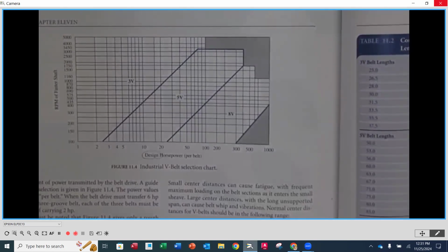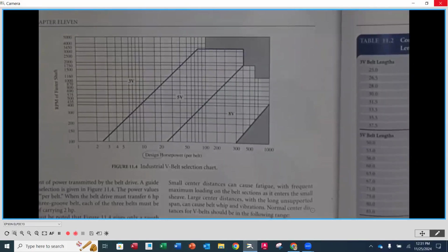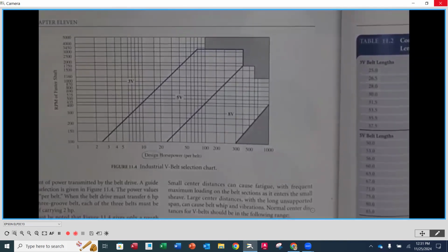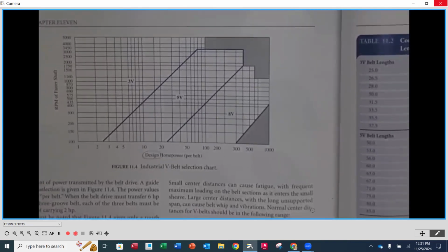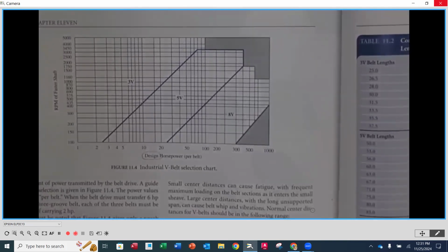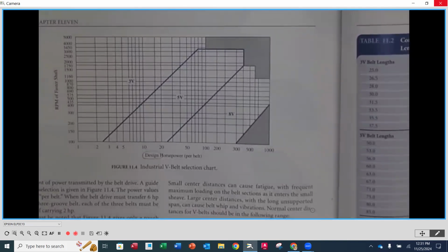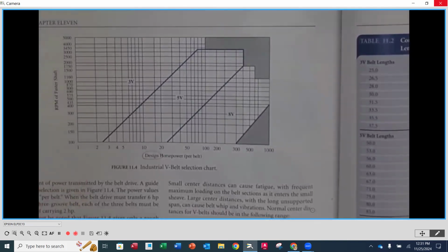a factor that is going to adjust the horsepower to reflect the volatility of the application. So for instance, if I'm looking at an automobile application as opposed to a drive for a rock crusher in a quarry, they're going to have 2 different levels of volatility, meaning overload. The rock crusher application is much higher than in an automobile situation, okay?